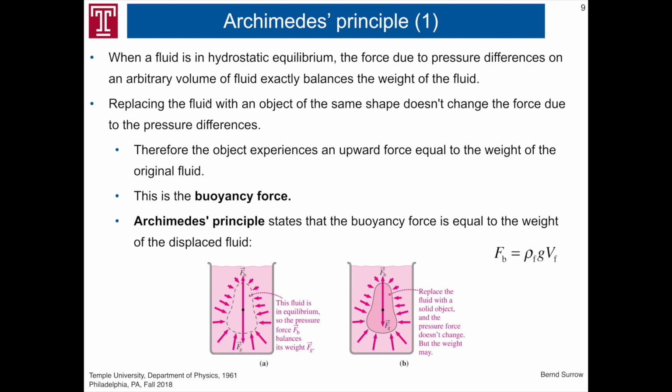When a fluid is in hydrostatic equilibrium, the force due to the pressure differences on an arbitrary volume of a fluid exactly balances the weight of the fluid. Now, replacing the fluid with an object of the same shape doesn't change the force due to the pressure difference. Therefore, the object experiences an upward force equal to the weight of the original fluid. And this is the so-called buoyancy force. Let me explain this to you in more detail here.